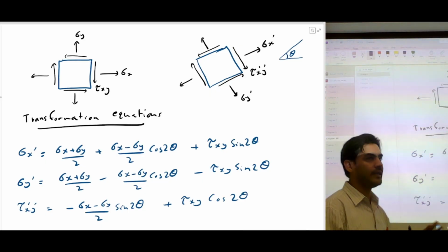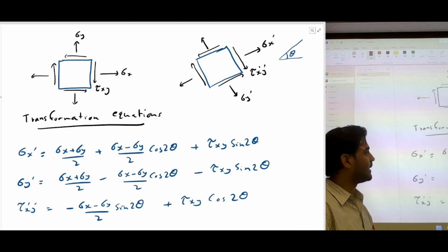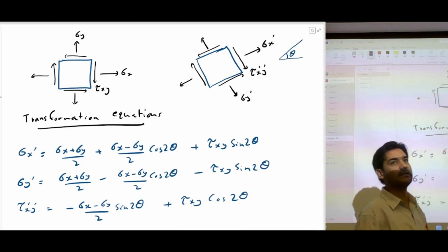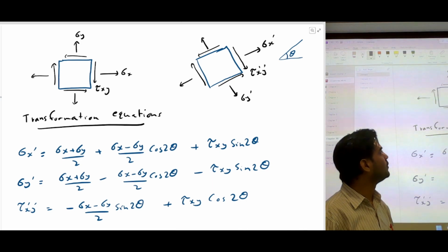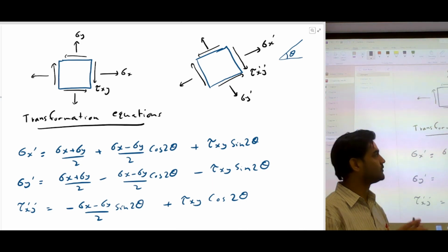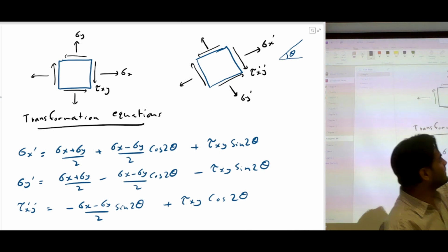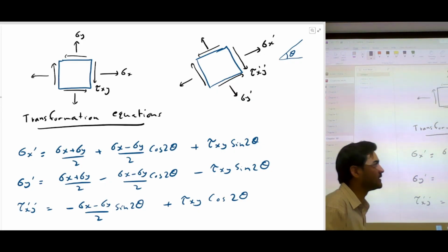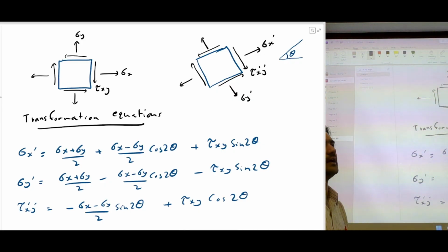So in this chapter, the stress transformation chapter and the Mohr circle chapter, basically the idea is you have to combine all those stresses and put those combined stresses into a stress element, because this will help you calculate the maximum stresses. If you rotate the stress elements, you're going to change those stresses. So what we are interested in is calculating the maximum stresses. Once you have those maximum stresses, you can figure out whether the material, machine, building, or any other component you are designing or analyzing is safe or not safe.